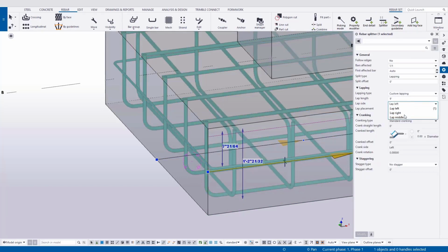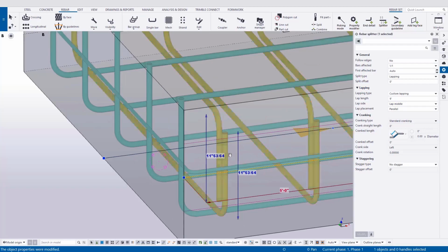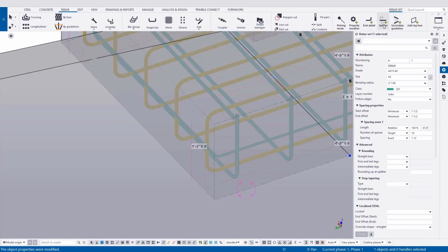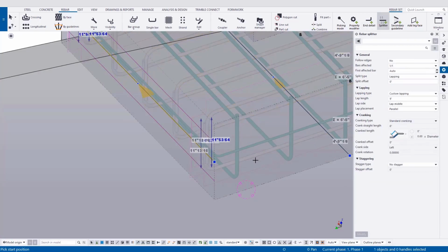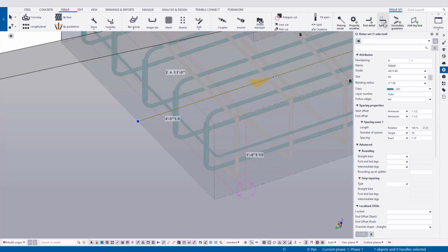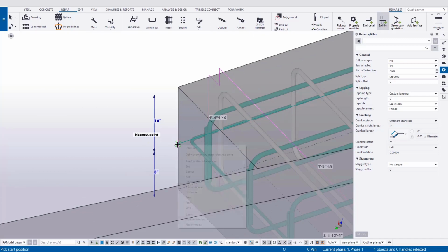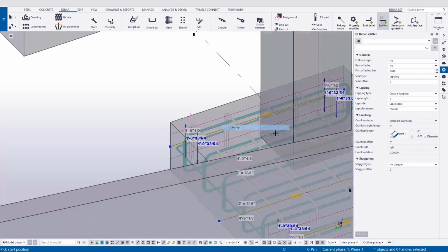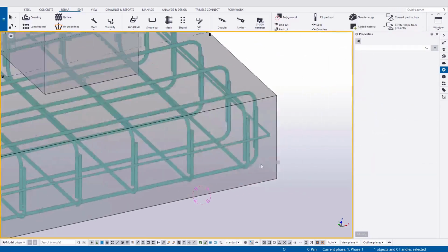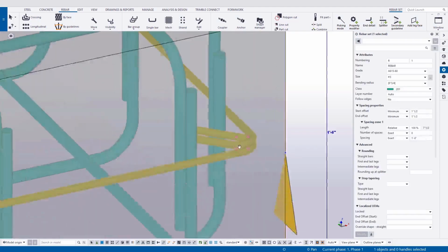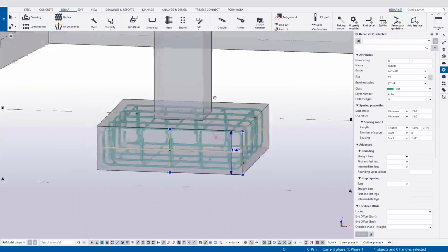This approach also lends itself to reviewing the reinforcement as it's being modeled, so it's easy to spot errors or design oversight in interaction in 3D space. With the native tools found in the ribbon, the mentality is to start broad and then refine as an approach. These tools allow for accurate rebar modeling, but with that, they do require a little more input and a little more time to apply than, say, with components. However, the result is far more specific and customizable. In reality, many detailers use a combination of both methods, where components are great for quick creation and estimation, and the tools allow for finer details in taking components across the finish line.